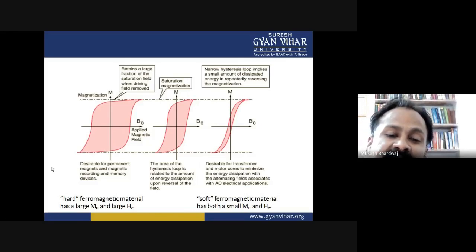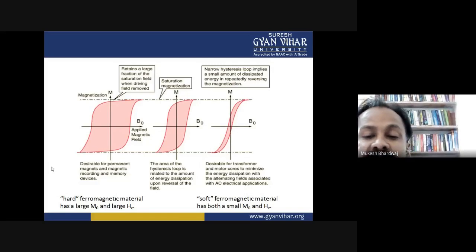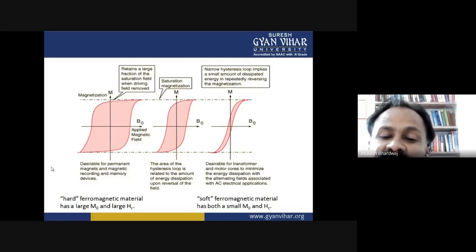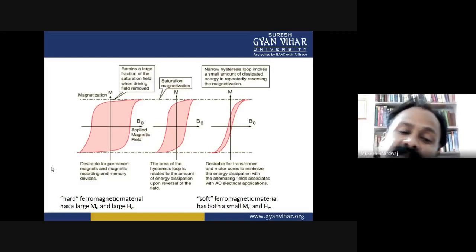The latter prevents the magnetic effect from being influenced or even destroyed by nearby magnets or external fields. This combined requirement is usually assessed by BH maximum, which should be large. Materials with large BH maximums are called hard magnetic materials.